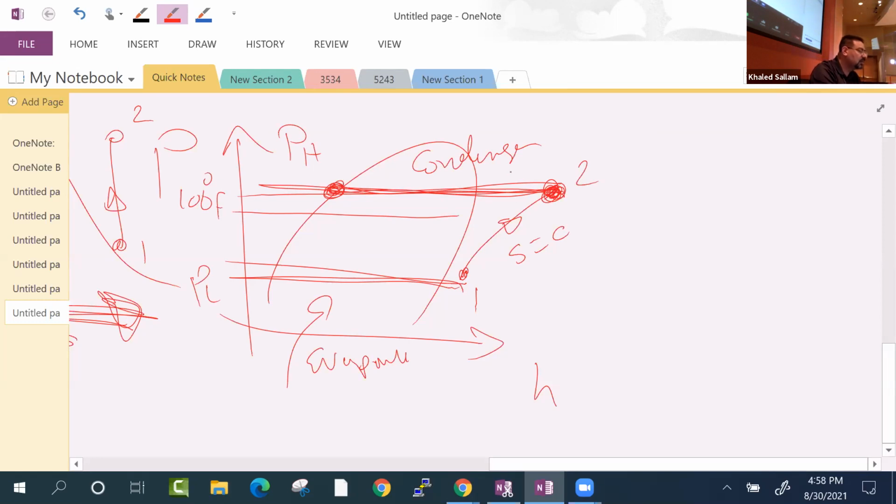So that hot vapor leaving the compressor gets cooled, becomes saturated vapor, and then gets cooled until it becomes saturated liquid. And the guy at the bottom, that's the one that goes to the fridge. That's the one that goes to the classroom. That's the one that's even colder than your low temperature. So let's say this is 70 degrees Fahrenheit. You are lower than it. And as a result, when you come here in that place, you are colder than that place. You are at 60, 50, 40. And you suck heat from them. And what happens? You evaporate until you become all the way saturated vapor.